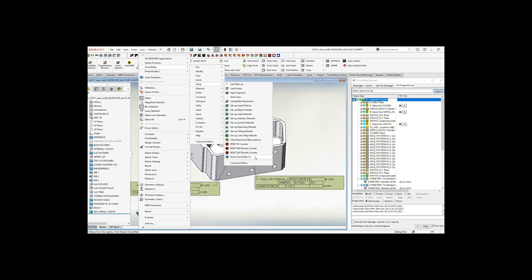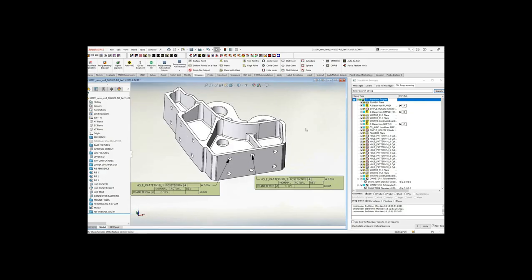So you can execute this command and then quit out of CheckMate right away and then start CheckMate back up. When you do start CheckMate up, always remember to use the CheckMate 14 desktop icon and not the SolidWorks icon, because it does do some cleanup of the ribbons. So once you execute that reset user interface, quit out of CheckMate, and then go back in and start it back up. Now if that doesn't work, you can try doing it manually.